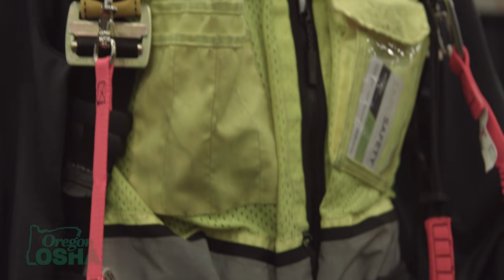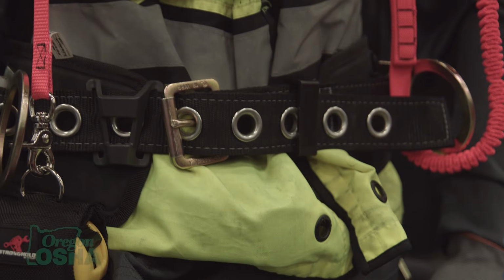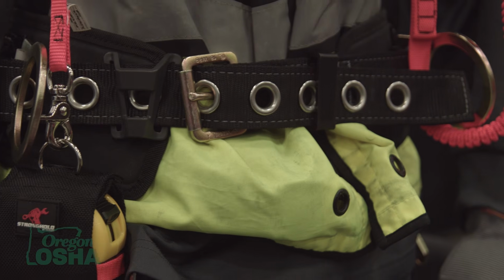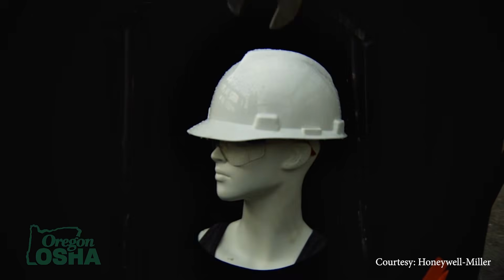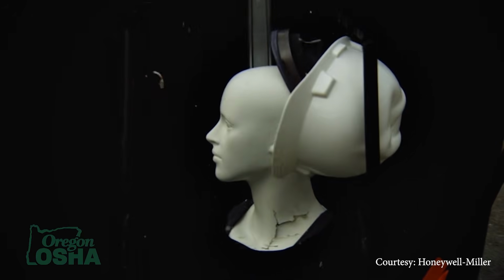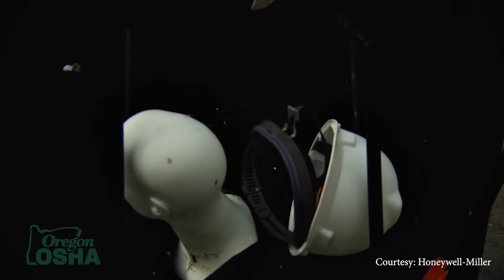Another way is to ensure that everyone who is working above with tools has equipment with some sort of lanyard. So if you're using a wrench or a screwdriver, there is a lanyard attached to that tool, so that if you were to inadvertently drop it, instead of falling all the way to the ground where employees are located below, the lanyard would allow it to drop 18 inches or 2 feet, and that's it. The employee who's using it can pick it back up and holster it appropriately.